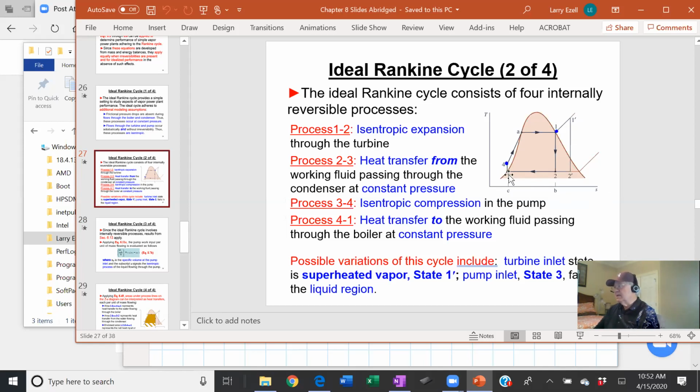The pump process is isentropic, ideal, and then you may be given an efficiency, but for the actual process, all work processes have to increase the entropy due to their inefficiency and irreversibilities. So the actual process comes down here and hits this line. It may hit right in here, may hit out in here.